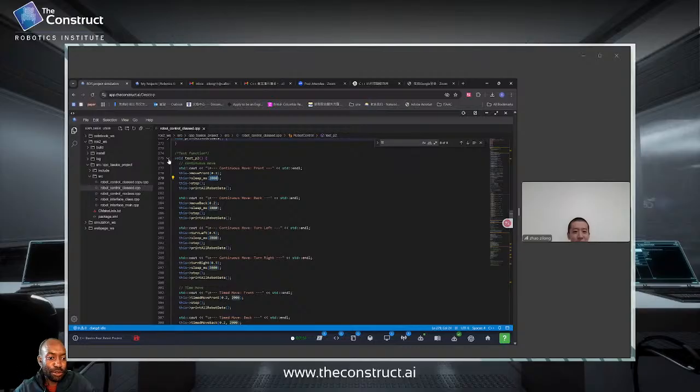And then you said you chose 2 seconds as the time that it has to go for. Is that right? Yes. Because when it starts, it will be in the middle, which means the front will be 1 meter and the back will be 1 meter. So I thought maybe 0.4 meters is good enough. And for the turn, it's like one angle. I don't want it to turn a lot or turn so fast. So it's still 2 seconds for the turn. So when you set the angular velocity to a particular value, it has to execute for 2 seconds as well. Yes. Okay, all right. This is just for testing.